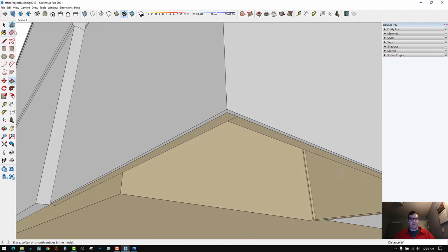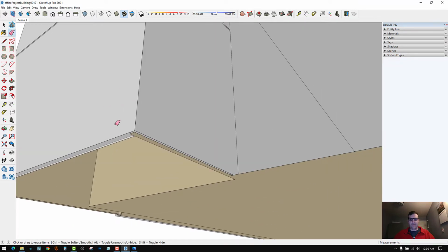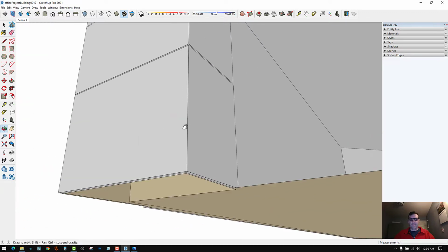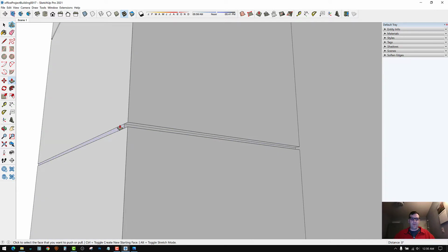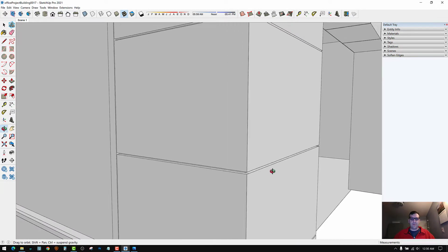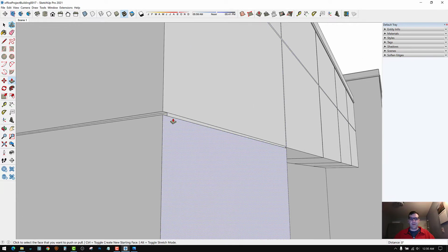These bottom pieces we can delete the extra edges that it created for us there. Yeah, this is looking good. So we're creating a half-inch by 1-inch deep crease that will help show up in our rendering software later on.